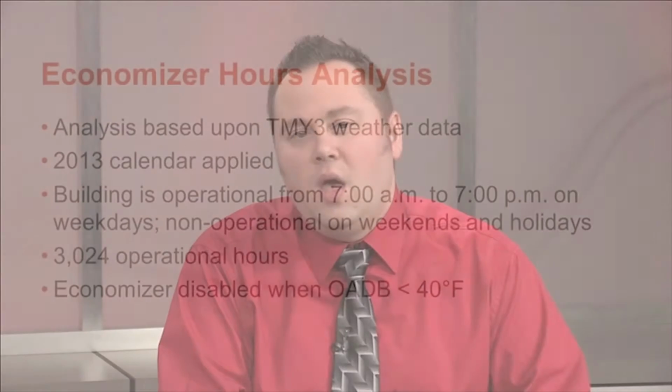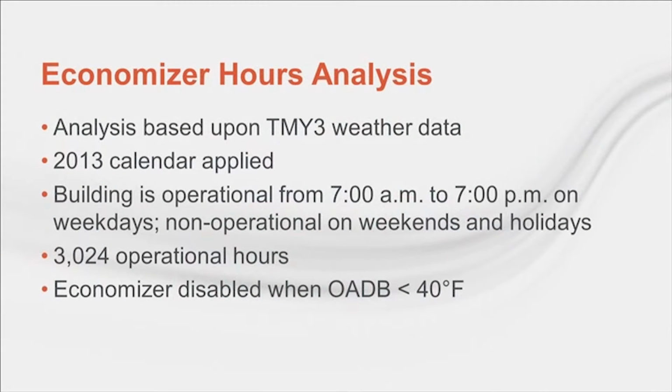One could evaluate a weather file to determine when the out-air dry bulb temperature is less than a high-limit shutoff, or one could evaluate when the out-air enthalpy is less than 28 BTUs per pound. We did just that for several cities in different climate zones around the United States.